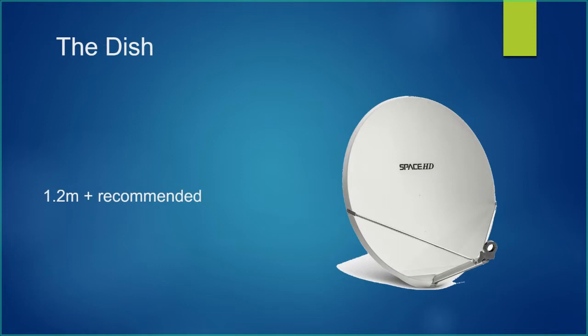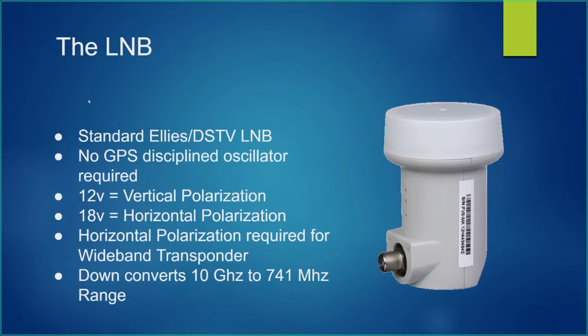But the same setup works, I'm using the same dishes for both narrowband and wideband. But that's something to keep in mind if you're setting up a new station from scratch. On the LNB side, your restrictions are a lot less for the DATV. Your simplest standard DSTV LNB that you can get at your local Mantech works beautifully.